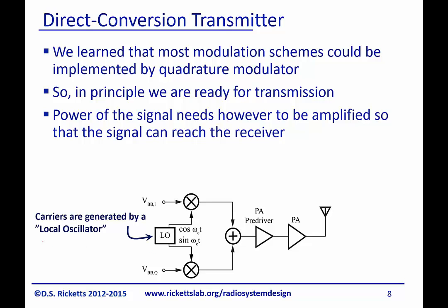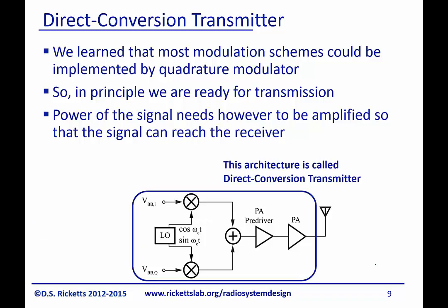And as I've used sort of throughout this course informally, and I guess we'll introduce it here formally, we call the oscillator that drives these two quadrature signals the local oscillator. And this just comes from the fact that it is the oscillator that's in the radio, and so if you will, it's the local oscillator that up or down converts the signal. And this architecture, as simple as it is, is called a direct conversion transmitter, and it is quadrature. Almost all of the digital communication we'll deal with involves a quadrature transmitter. If the input signals here were analog, this would just be a direct conversion analog transmitter. So there's nothing really different between analog and digital from a hardware standpoint for this direct conversion. But we introduced this because we're going to be going into more complicated architectures in just a moment.